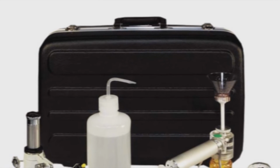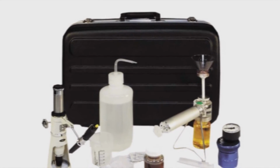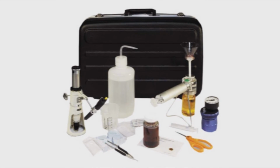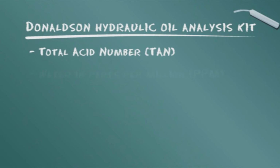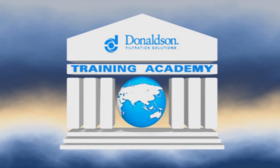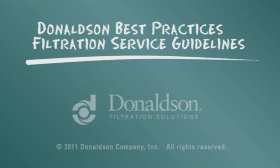There is also a Donaldson hydraulic oil analysis kit for basic on-site monitoring of systems. The kit is typically used on industrial and heavy-duty equipment. It provides TAN, the total acid number, water in parts per million, and provides the ISO particle count. This servicing information is provided as a best practices guide. It is not, however, intended to replace or supersede the service instructions supplied by your engine or vehicle manufacturer.